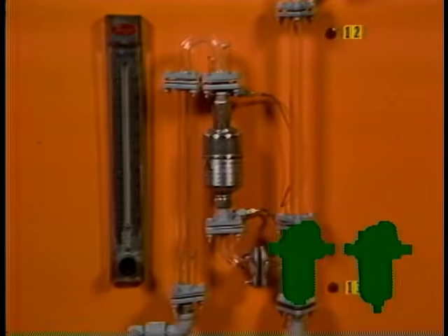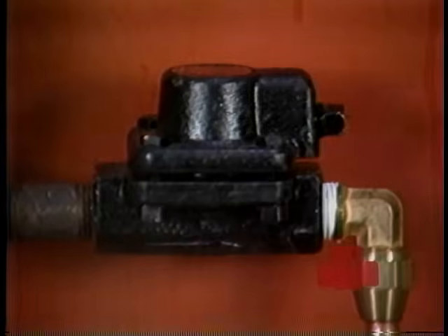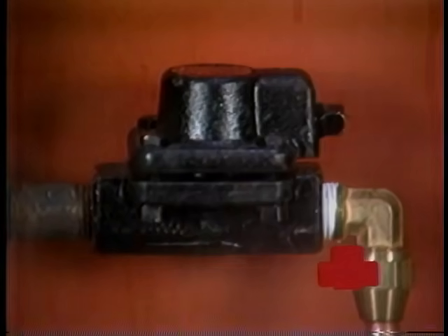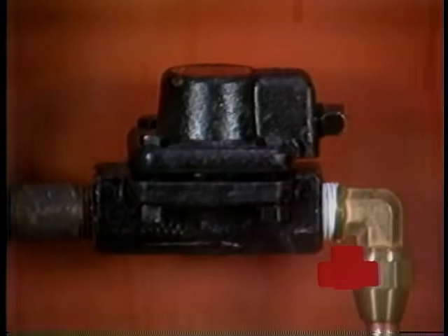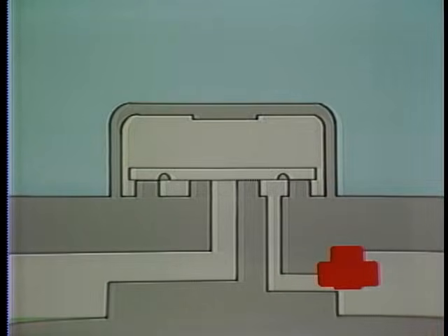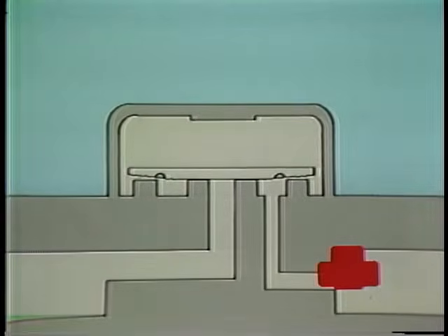the valve snaps shut. F&T and bellows steam traps have modulating outputs at very low loads. In these traps, the opening and closing forces tend to balance out as the load decreases and the trap doesn't fully open or close, but modulates with the condensate flow. The disc trap is not recommended in situations where the average load is less than 3% of the trap's rated capacity. Live steam causes the trap to cycle frequently, prematurely wearing the seating surfaces.